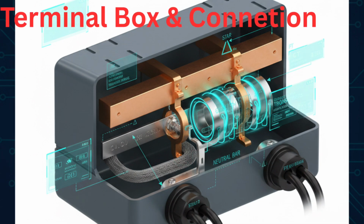Terminal box and connections. The terminal box contains the stator output leads and the connection links for star or delta configurations. It also houses the neutral bar and mounting arrangements for current transformers and potential transformers used for protection relays and metering. Proper earthing of both the alternator frame and neutral point is essential for safety and earth fault detection.